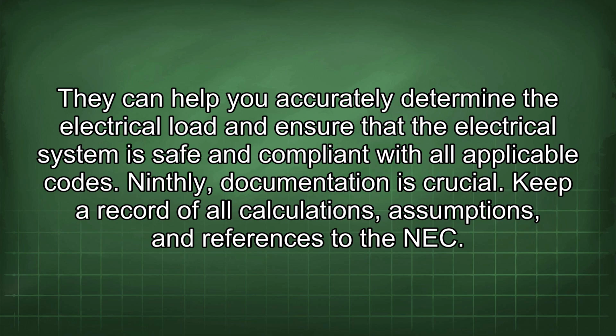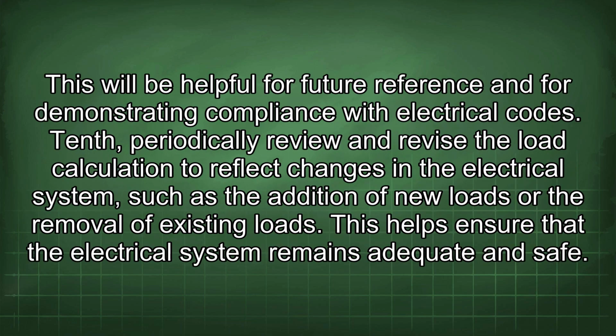Keep a record of all calculations, assumptions, and references to the NEC. This will be helpful for future reference and for demonstrating compliance with electrical codes. Tenth, periodically review and revise the load calculation to reflect changes in the electrical system, such as the addition of new loads or the removal of existing loads. This helps ensure that the electrical system remains adequate and safe.